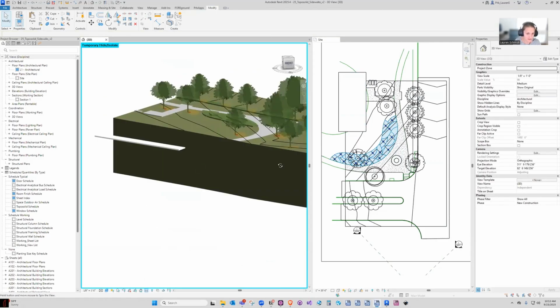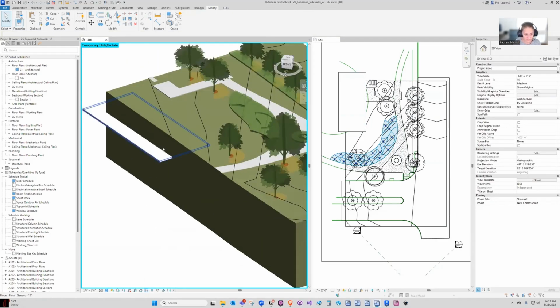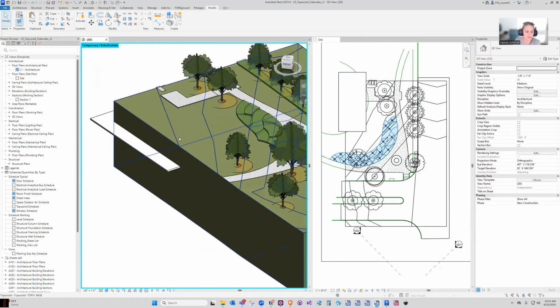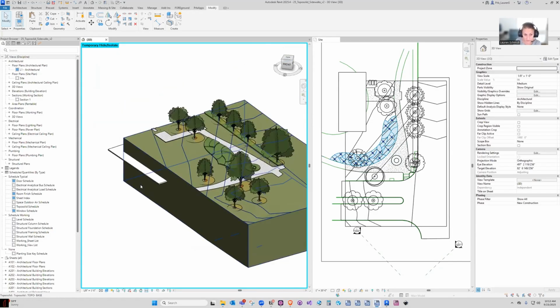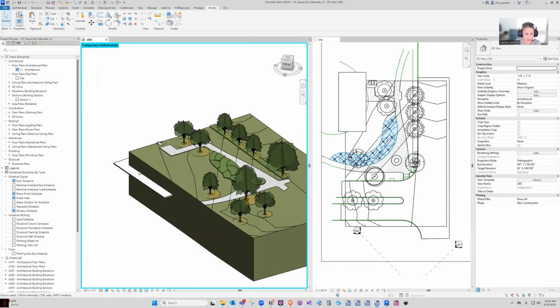You'll see I haven't excavated anything now that I've removed that as an excavation. I could use that building floor as an excavation tool, but most of the time you're not going to have a giant floor mass as you're building. What you typically do, and what you did with building pads, is you put a pad down at basically the basement level. Depending on the building, you'd often have different pads stepped around wherever your basement is stepping around.